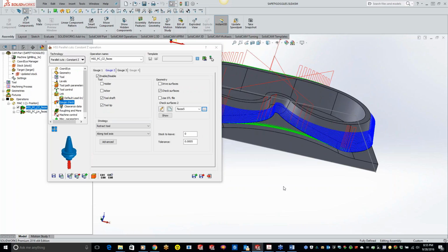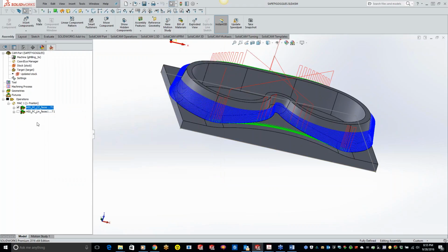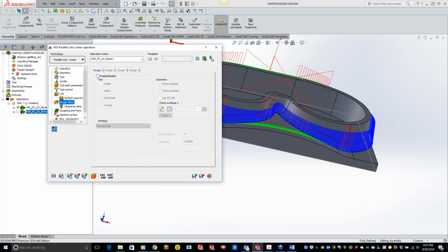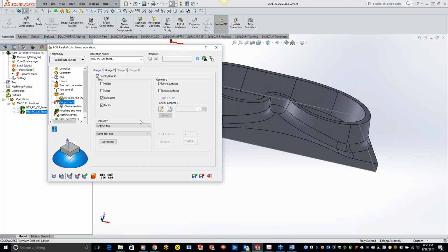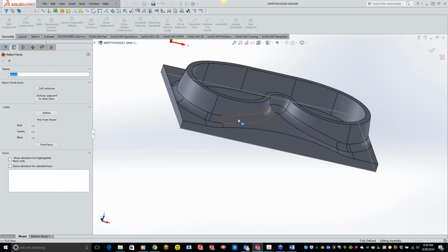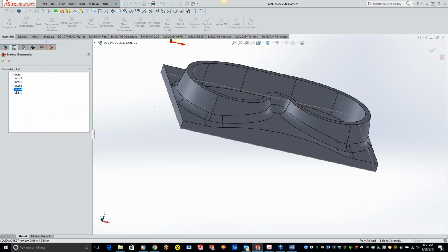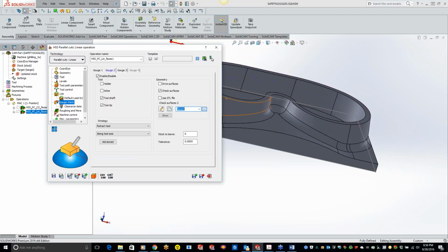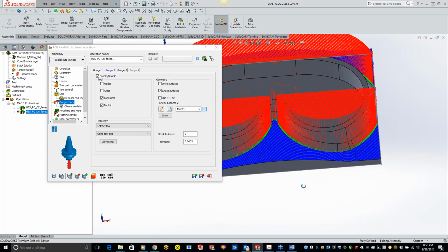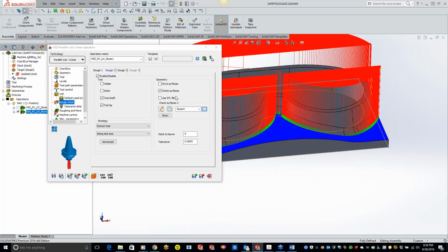So that's turning on the gouge right there. And let's come over to the other one. Let's turn off that toolpath here. Let's turn on our gouge for our drive, and turn on our gouge 2 for our check surfaces. And basically, I don't want it to touch, well, instead of clicking all these, I know I already picked them. Let's see, that one right there. So I don't want to touch any of those surfaces. And now we are 100% not gouging into our part.